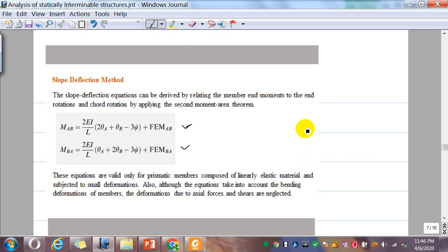For example, if you consider a continuous beam and a section in the middle, there will be M, and then there are reactions RA, RB, and there will be some axial force that will be balancing each other, or it could be zero. Then you have the load and this axial force as well. So now there are 6 unknowns. Except for the axial load, which could be mostly 0, if you find these 2 moments, then you can find the 2 reactions.